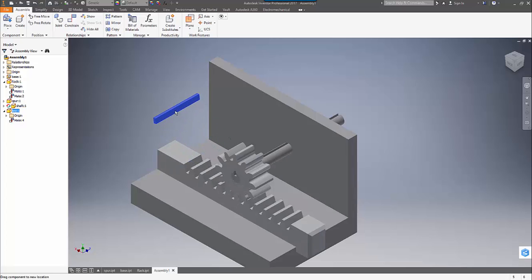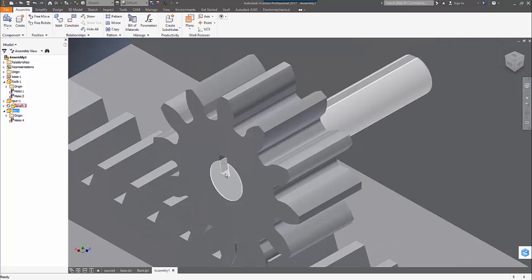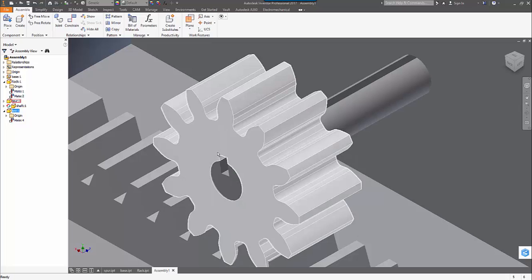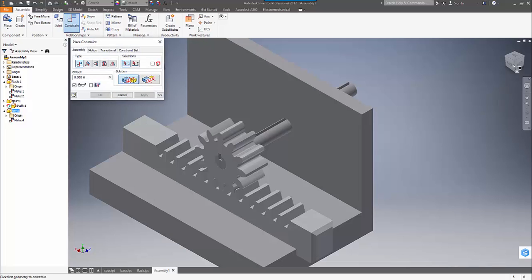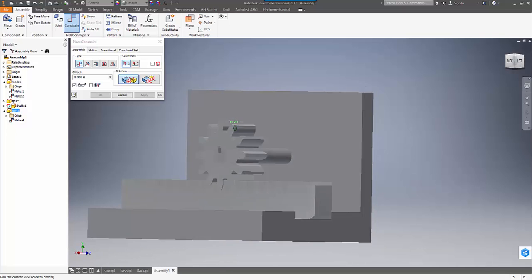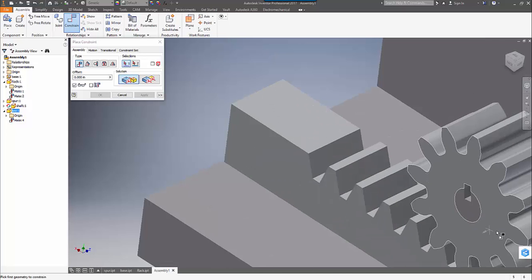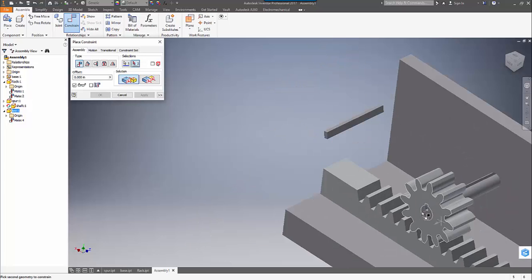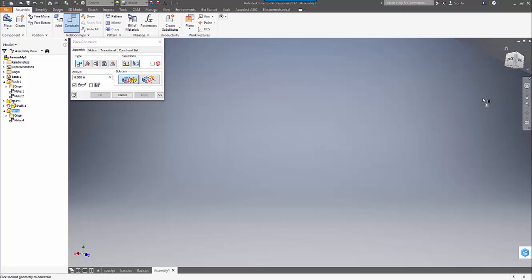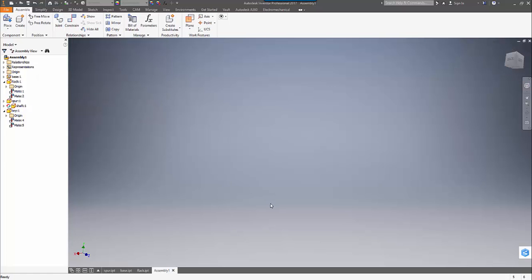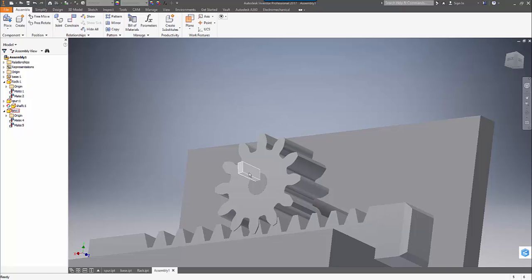And so the other constraint that I need to place on the keyway is the bottom of the keyway to the bottom of the slot, the keyway slot. So the bottom of the key to the bottom of the keyway. And so we're going to constrain a mate constraint to that. And so we'll pick the bottom of the keyway and flip this around, and the bottom of the key, and we'll apply it and choose cancel. So again, now the keyway is still there. I can still move the keyway in and out, but you can see how it's now connected.